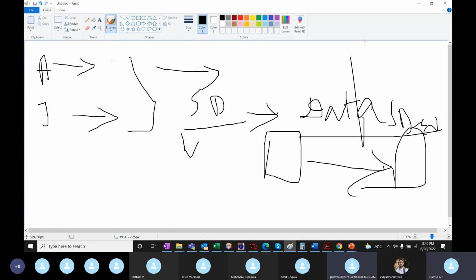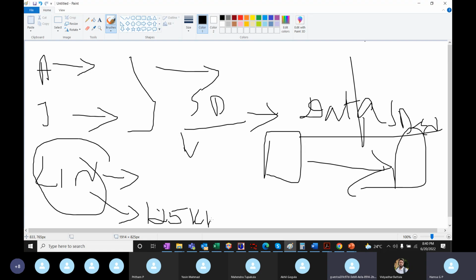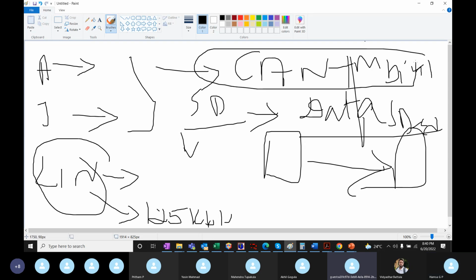If you remember, we were just talking about the LIN protocol, which was a master and slave communication. The speed of LIN is very less, which is 125 kilobits per second, and in practice it is even less. The CAN protocol speed can go up to 1 megabits per second. So now tell me, which one do you prefer? The client has to do the best for us, so he is going to select the CAN protocol on a critical basis. That's where the speed comes into the picture. CAN protocol will be used for the critical functionalities, and LIN protocol will be used for the non-critical functionalities.